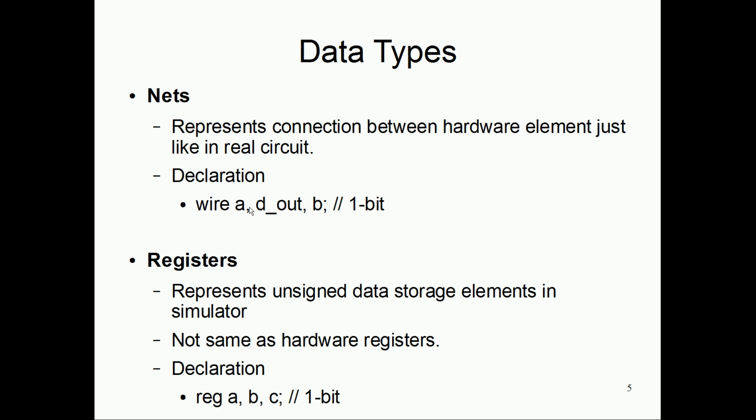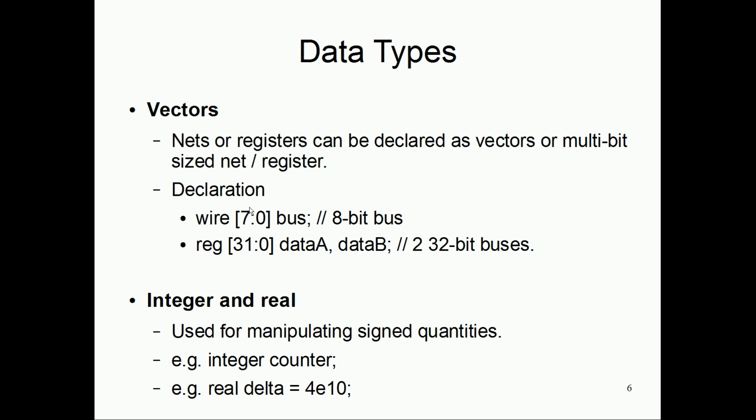And again, if I just declare a register variable without any dimension, by default it is 1 bit. Compared to Java, for example, if I define something like integer a, by default it is a 32-bit storage, but here reg a means 1-bit storage, where a means a 1-bit representation of the signal.